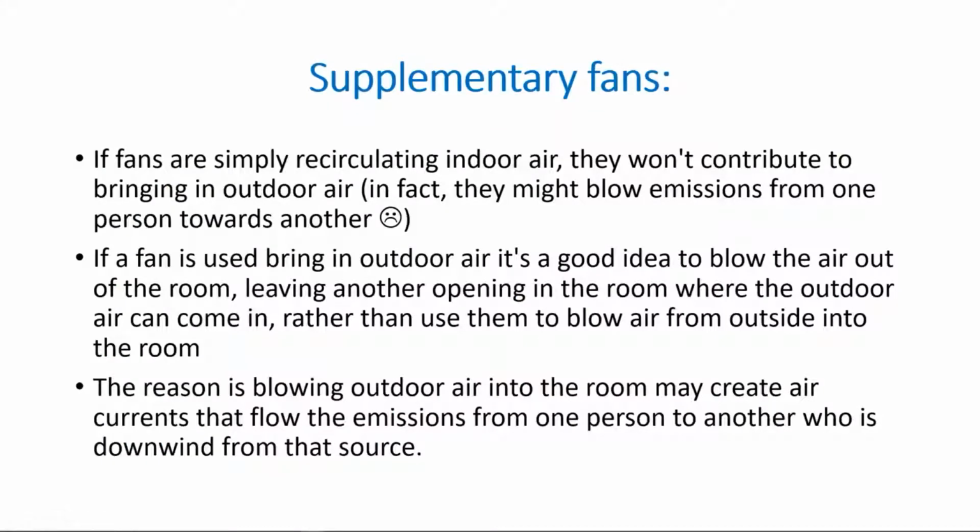Supplementary fans. If fans are simply circulating the air, they won't contribute to bringing in outdoor air. In fact, they may blow one person's emissions towards another person, which is not a good thing to do. So if you're using a fan to bring in outdoor air, you don't want to put it in the window and blow it in.